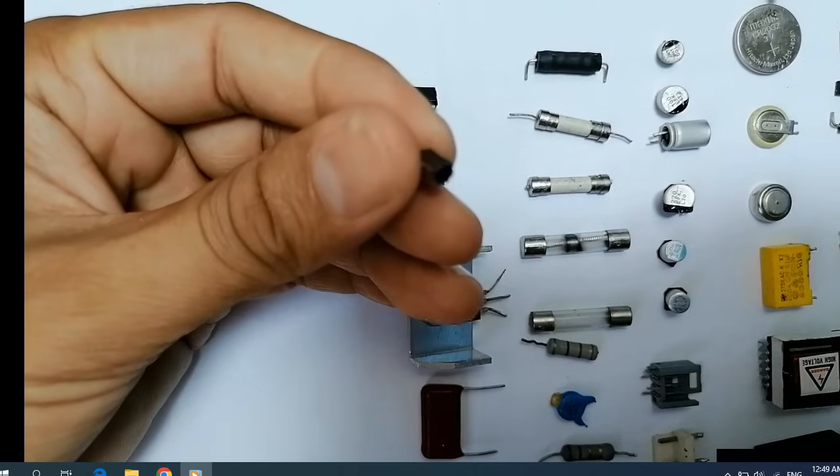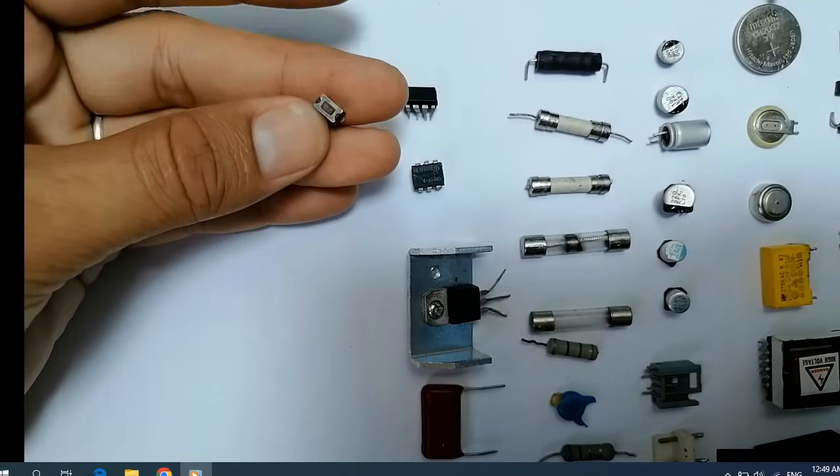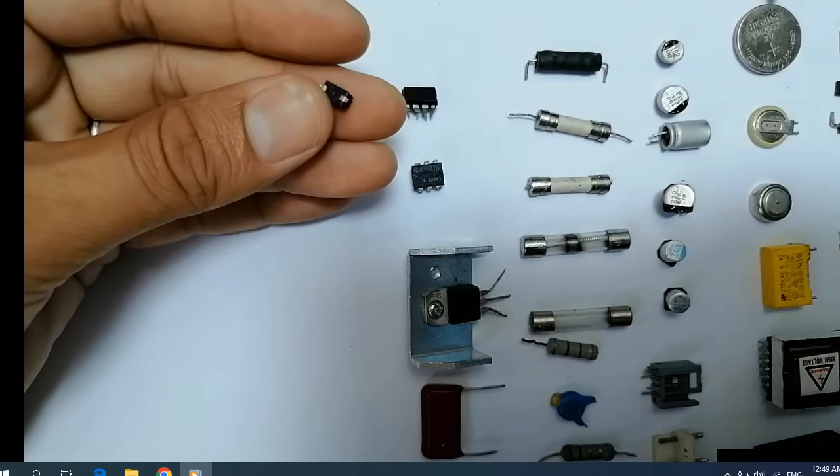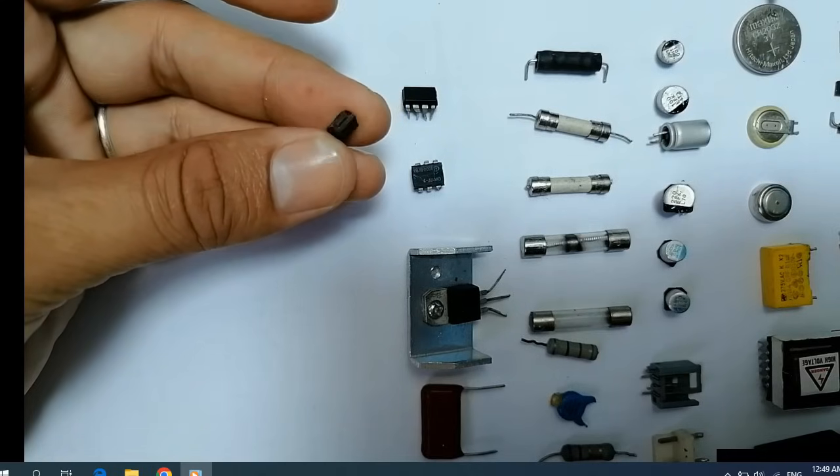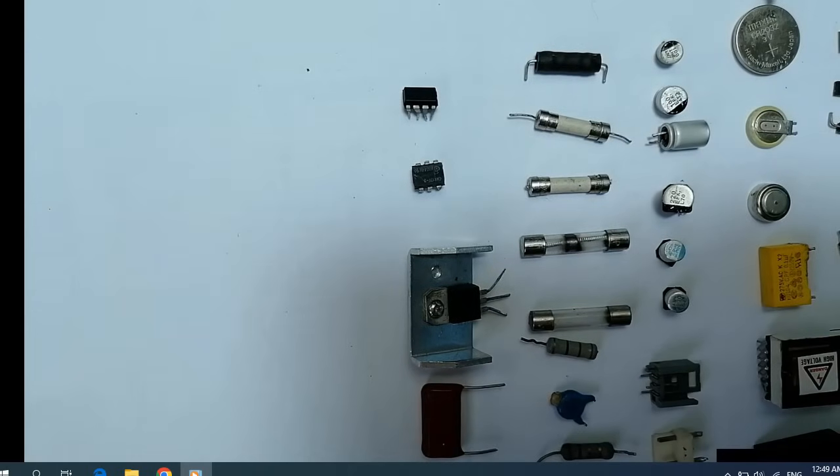And over here we have another switch. Basically the switch has just 2 terminals, okay? One terminal connected to ground, and the other one connected to 3.3 volt. Once you click it, you shunt between 3.3 volt and the ground, and the laptop will turn on.